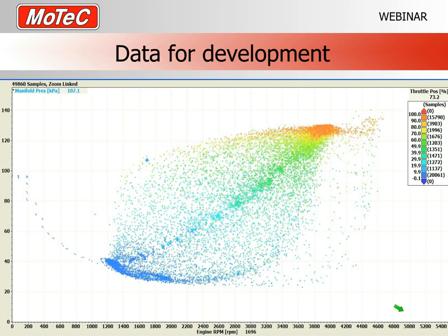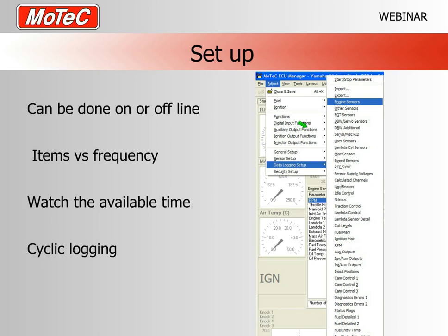And the data is coloured by different throttle positions. So 100% throttle, 80% throttle, 40% throttle, they've all got different colours. So we can see what boost this engine makes at what throttle position, and we can see how the RPM and boost are related. Just another way of using a data analysis program like i2 to help you learn interesting information.